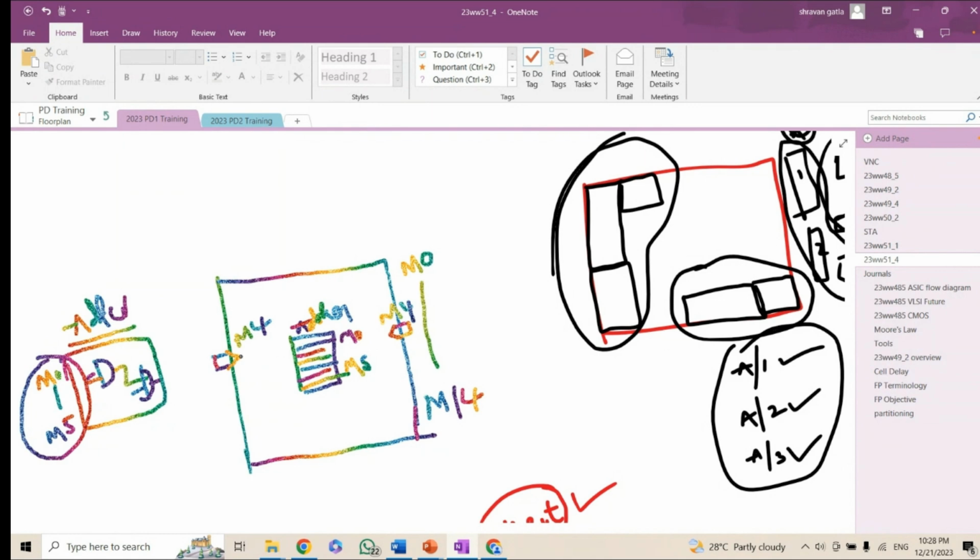And what does it do? The tool routes till here with M4. And it will detour. You remember the word detour, D-E-T-O-U-R. Okay, what happened? M4 is routing, and it will go to M5. Instead of a straight line on M4, it is detouring to M5. Again, it will go to M4. Here no blockage, right? M4. Again, it will come down to M5 and M4. So you are seeing the issue here, right?